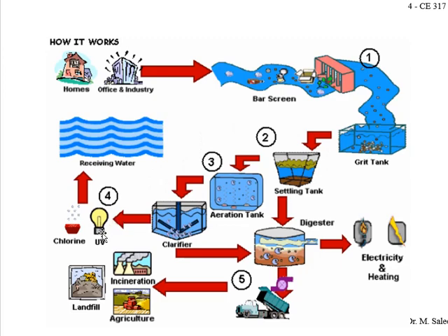After that we go for the tertiary treatment. In the tertiary treatment, we do disinfection because there are still some bacteria which are harmful for us. If you remember, those bacteria are called pathogens. These bacteria can be killed or removed by disinfection. Disinfection can be done by adding chlorine, by using UV radiation, or by using ozone. There are many methods. After that, the water will become very clean. So now you can discharge this water into the river or other places, and it will not be harmful for anybody, or you can even reuse it for agricultural purposes like growing crops, plants, and other things.